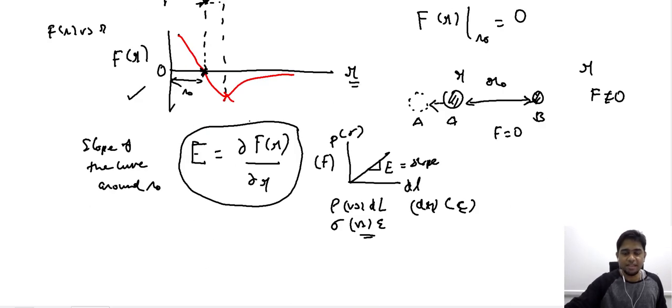So what essentially we have done is we have considered the behavior of a material in the atomistic scale, and we were able to relate that behavior to what we observe at the macroscopic level. In addition to why the material gets back to its original state and how much load we impose on a given material to bring about an elastic change, it is also possible for us to quantify the Young's modulus from the atomistic perspective.